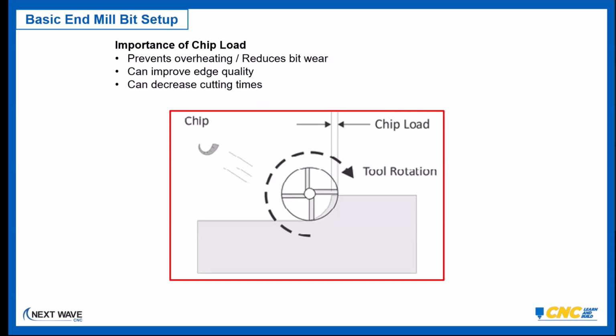I've worked with people who sometimes run their machines at like 50 inches a minute. And frankly, unless you have an SD tool, on the HD tool, that's simply slower than you need in most cases for general cutting. I run my HD tool with a 3-horse spindle on it. And when I had the 2-horse also, always in the neighborhood of 80 to 150 inches a minute. And sometimes I go all the way up to the max of 200 with some cutting.